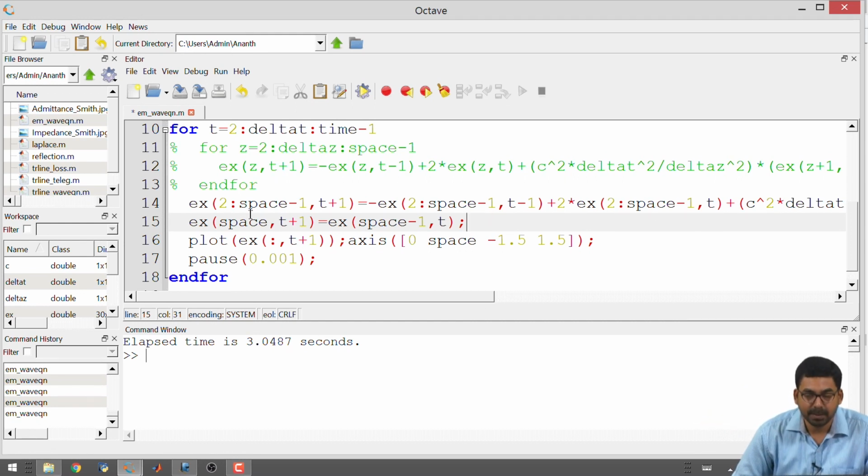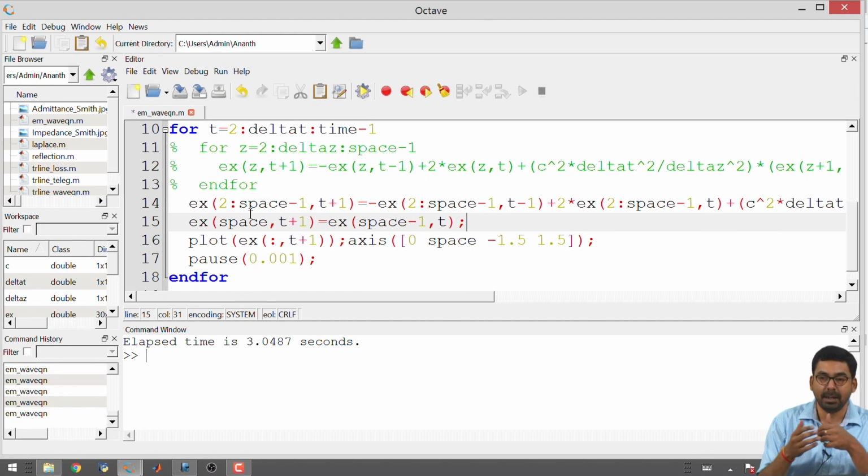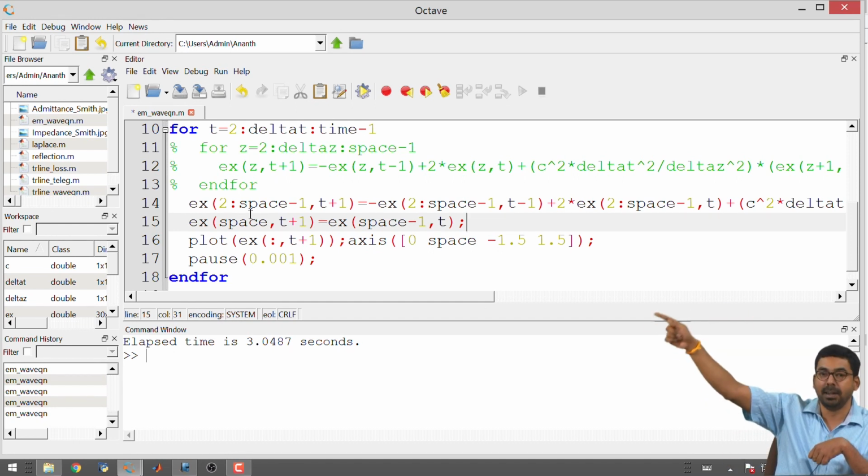Implicitly your wave equation is doing that, but when it encounters a non-uniformity, it also calculates accurately and tells you that there is some impedance mismatch, so it is bouncing back. So, what you do is you bypass the wave equation for the right side most edge. In order to make it look like the wave is traveling from one point to the next point, all you need to do is in one instant of time, you have to move the peak to the next point in space at the next instant of time.